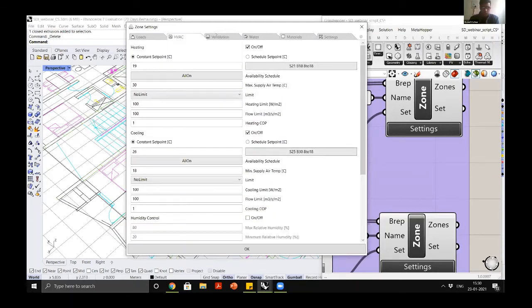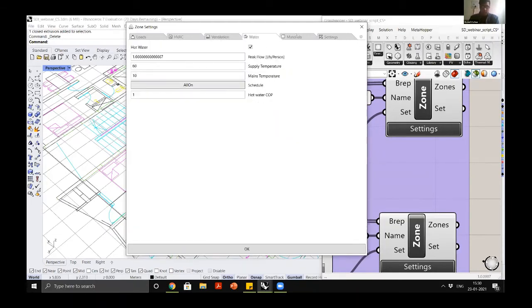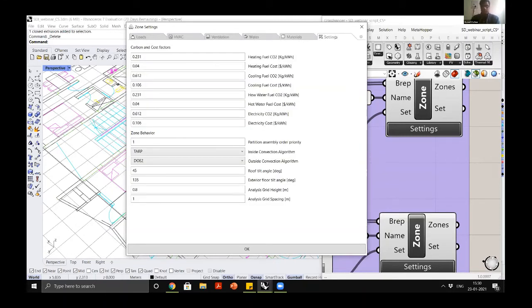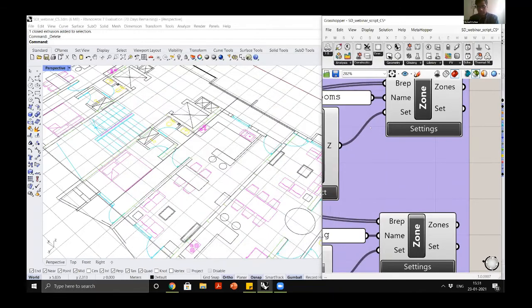So essentially the settings tab, the zone settings tab, you can create your own templates. You can use the library that is available. You can modify your library, and this is like, again, Shubham mentioned that it's a one-time effort. You will have to invest on this, and once your inputs are finalized, then you can keep tweaking them parametrically to understand the implication of various energy conservation measures.